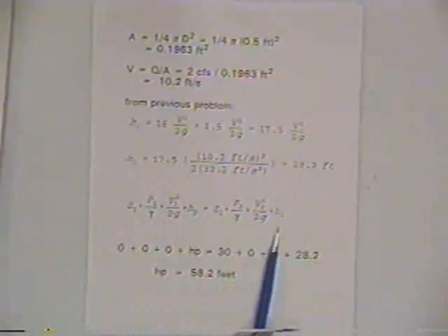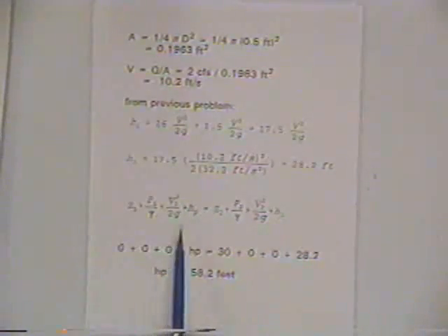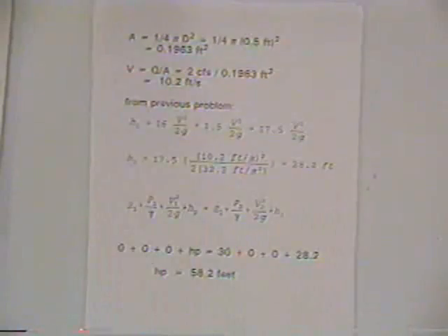Here's the energy equation again, the same old energy equation that we've used starting with the pitot tube and continuing to use again. In the previous example, the head loss got significant, so we included the head loss term. Now we've got the complete equation. We've got the pump head term as well, which is going to be non-zero. And so we plug in what we know.